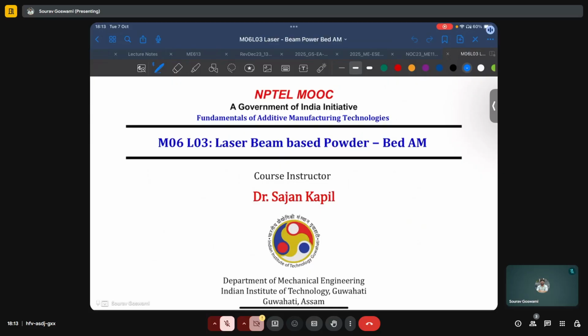But they may not be able to very faithfully recreate fluid flows inside the molten pool, or if you are focused more on the micro scale, then dendritic features or microstructural features. However, they are suitable for even part scale, or at least for tens of mm.